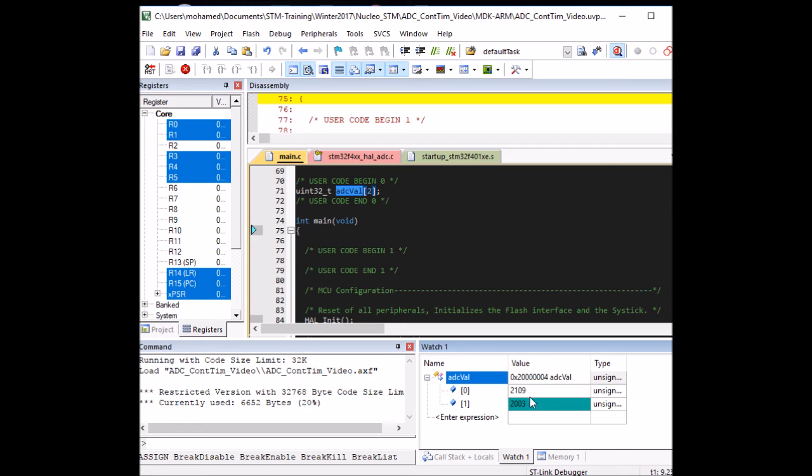Okay, good. I can see them positioned in the middle, so I know 12-bit resolution is 4096, and this one is 2000, which means it's in the middle. Now let me move my X axis and see how it changes. Okay, good. So it goes down to 0, and it goes maximum around 4096, which is good. And now my Y axis, same thing, goes down to 0 and up to 4096. Perfect. So this is working great.